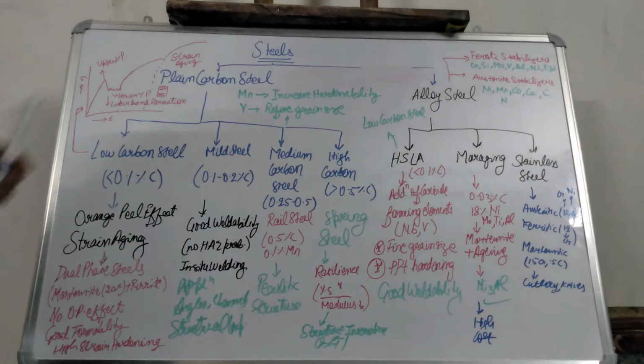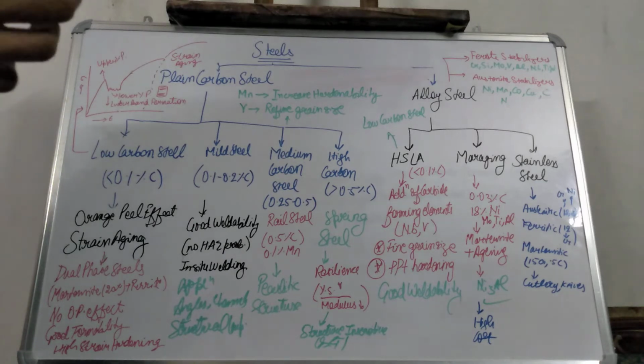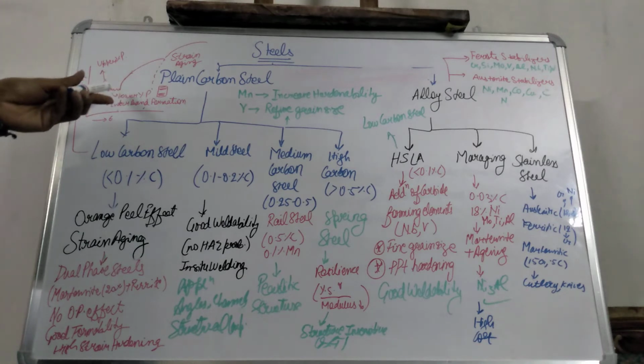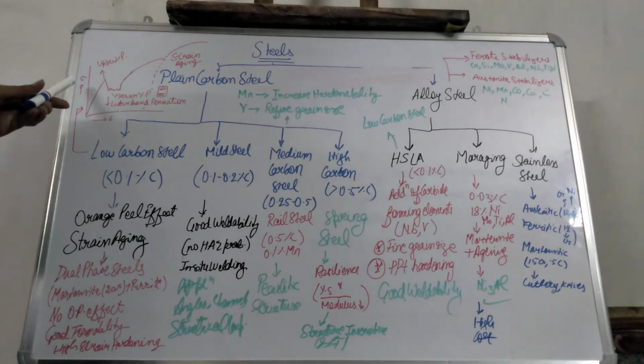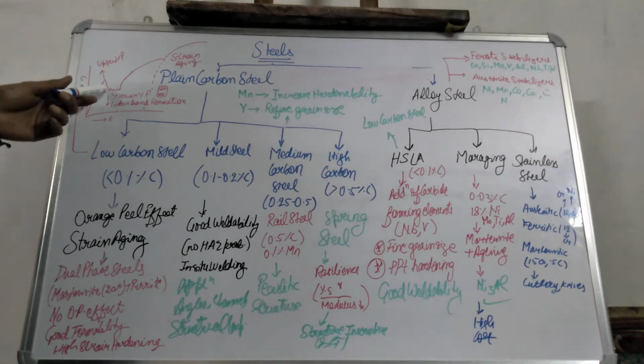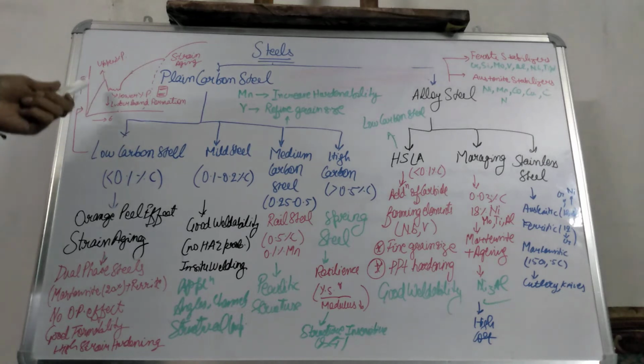That is the formation of various bands in the material at different locations, and they propagate to extend the deformation throughout the material. This deformation is generally called yield point elongation. There is a sudden drop in the yield point, and at this point there is a large elongation at a constant stress, and this is termed the yield point elongation.